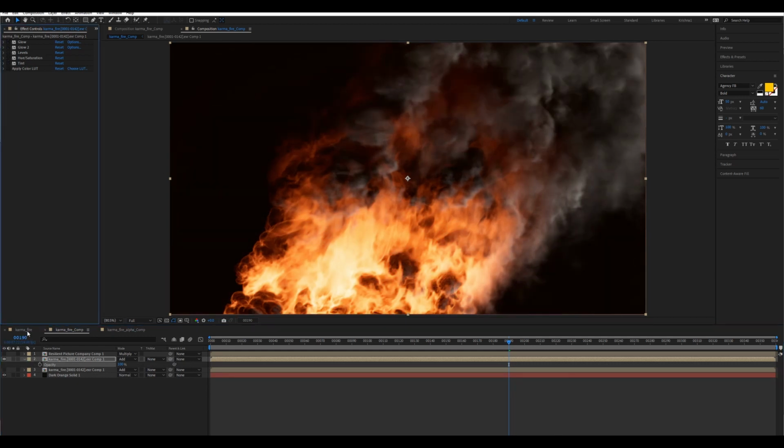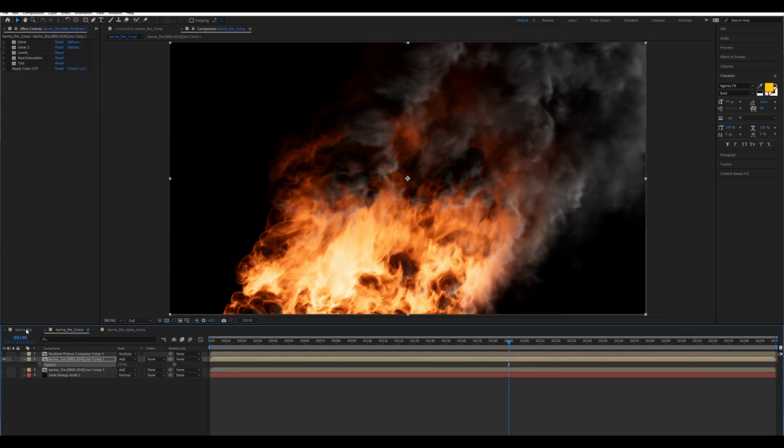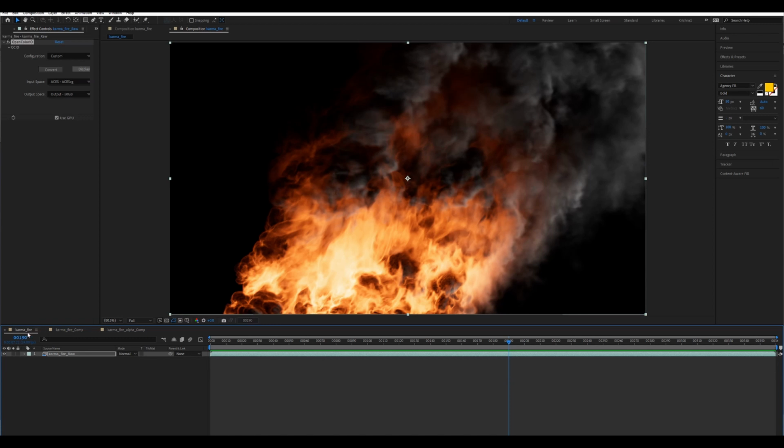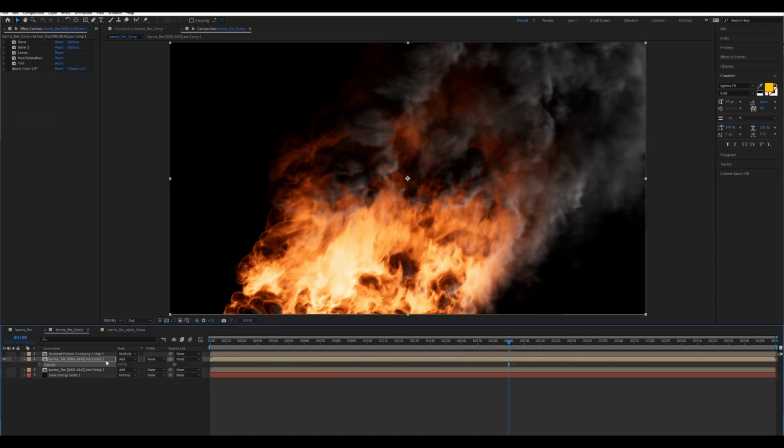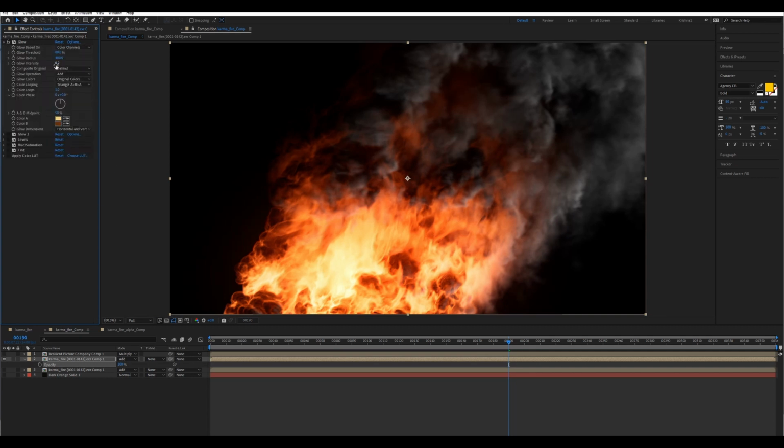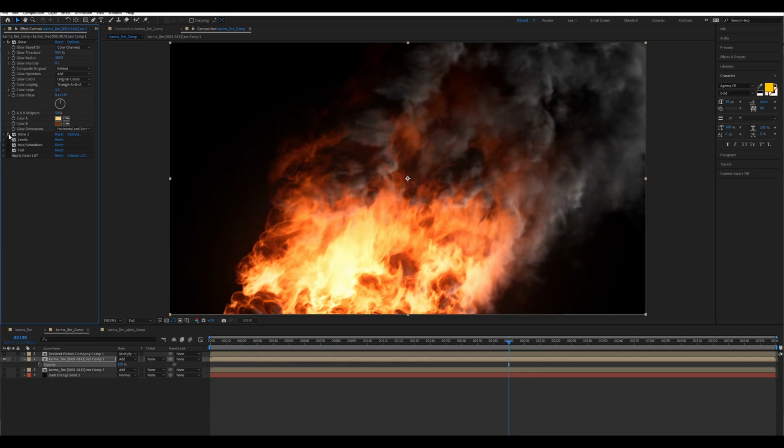So without it, it's just basically the same as this one. All right, except that one. If you look at these 2, they're identical. So I wanted a glow because this looks great, but fire needs a glow. Okay, simple as that. So I added a first glow, which is very subtle because the glow intensity is 0.2. But if you notice, the radius is 400. And the second glow, the radius is 800, but the threshold is 27.5.